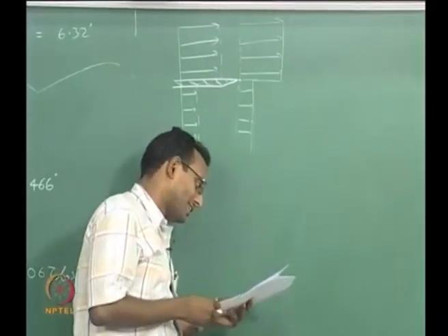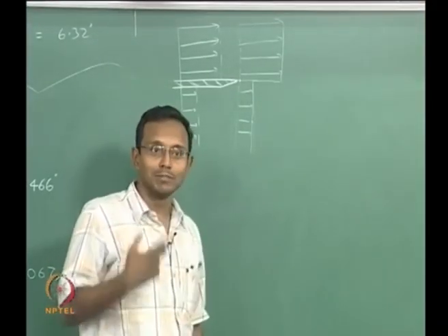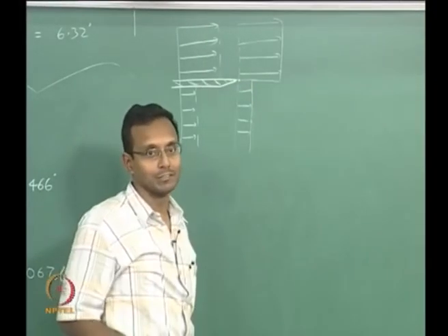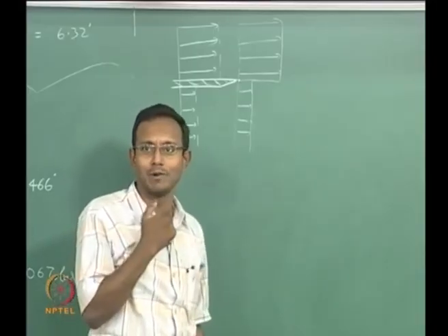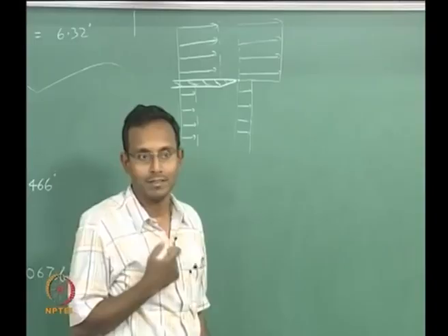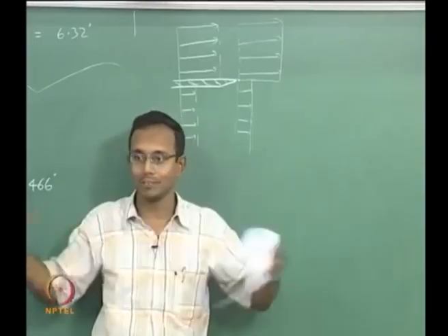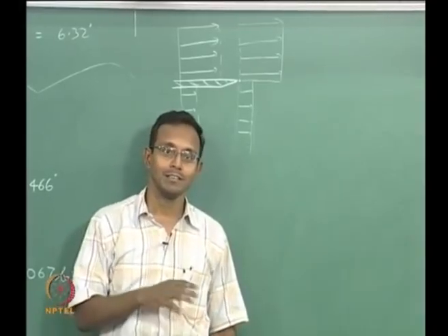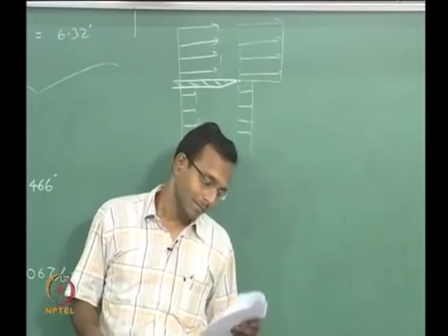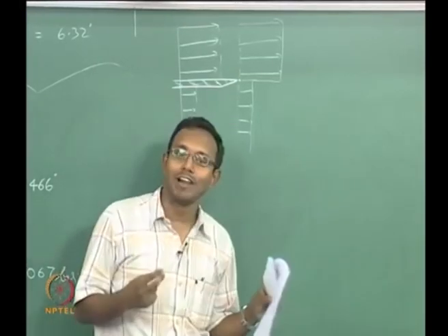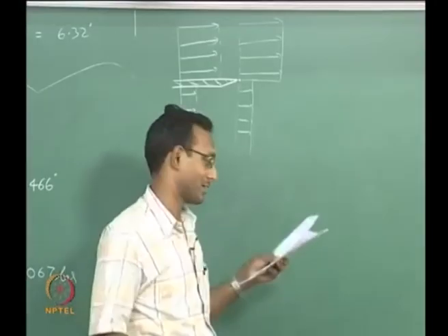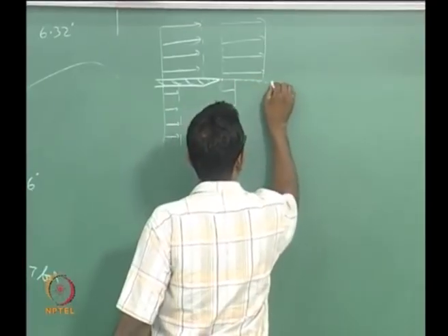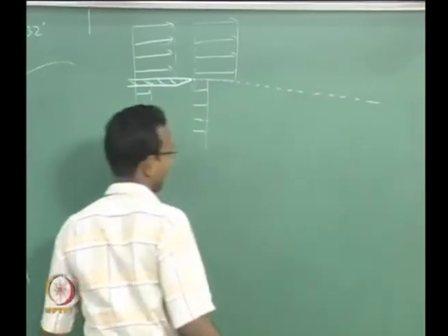While it is getting convected, viscosity comes into play and wants to take that vorticity and distribute it in every direction, up and down, all directions. Every other place it is 0, only one guy has all the vorticity, and viscosity does not like it. So it takes it from that person and gives it to the immediate next person, and it just diffuses out from there, and eventually everybody has the same amount of vorticity. If there are so many fluid elements, they will all have almost 0 vorticity. Now, some distance downstream, I will draw a dotted line going slightly downward, we will come back to that later.